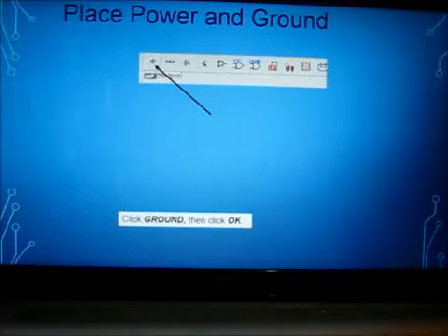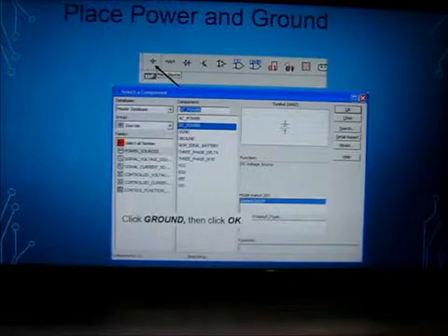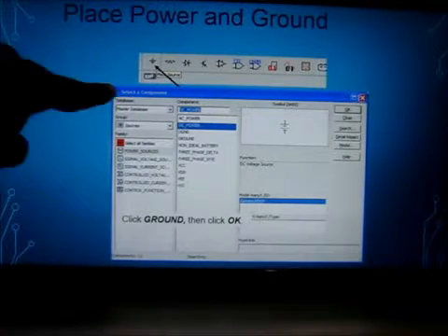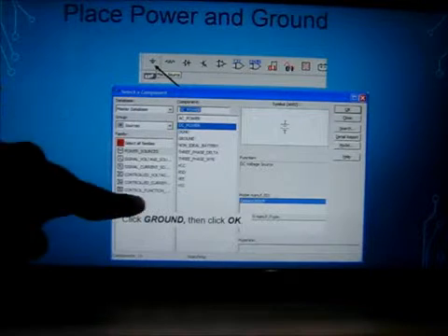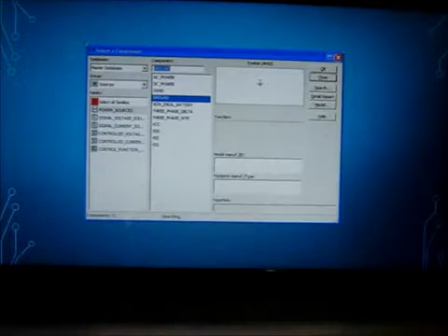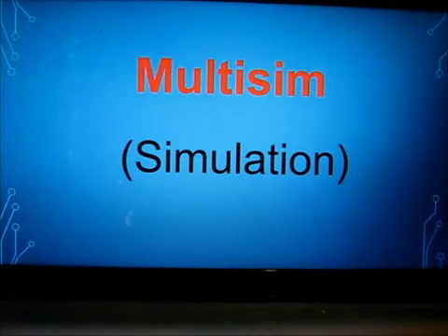Then we have also read about placing the components on the workspace, that is we have to right click on the workspace, that is the circuit window, and then we have to choose place component. This window appears, select a component. From this we have to select one or more components according to our requirement or our design, then we place them into our circuit board.